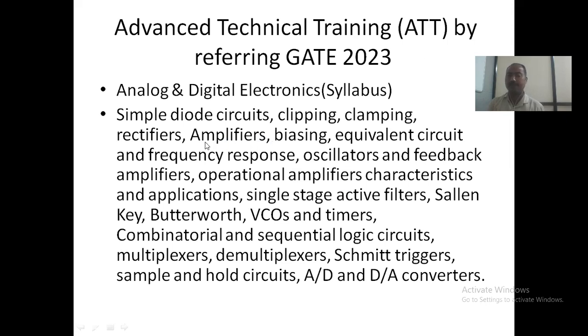When negative feedback is used in an amplifier, it reduces the gain of the amplifier. This is not acceptable in an amplifier, because we designed the amplifier only to increase the strength of the input. But one important thing happens in this case: it reduces the gain, but it stabilizes the gain. Stabilizes means it does not vary, right? That's why in your amplifier, we use negative feedback.